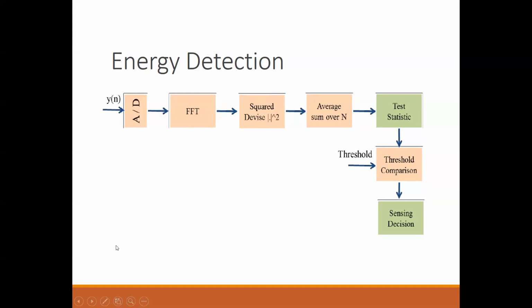That is the reason, for example, if you think of the discrete time Fourier transform and the fast Fourier transform: the fast Fourier transform is just an algorithm, an implementation of the discrete Fourier transform. So you have two things, one is the DTFT, another is the DFT. DFT is the samples of DTFT. You represent the DTFT as X of e to the j omega, and the DFT X of k, where k is 0 to N minus 1, is N equally spaced samples of the continuous function X of omega. I hope you can visualize what I am saying.